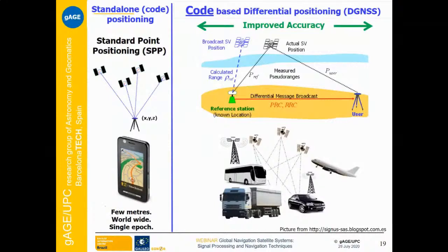What we can summarize: the accuracy is a few meters, the coverage is worldwide. We can do this standard point positioning everywhere, even in the middle of the ocean, and it's single epoch. Immediately after turning on the receiver, we have the final positioning. We will see that in the next positioning techniques, this is not the case.